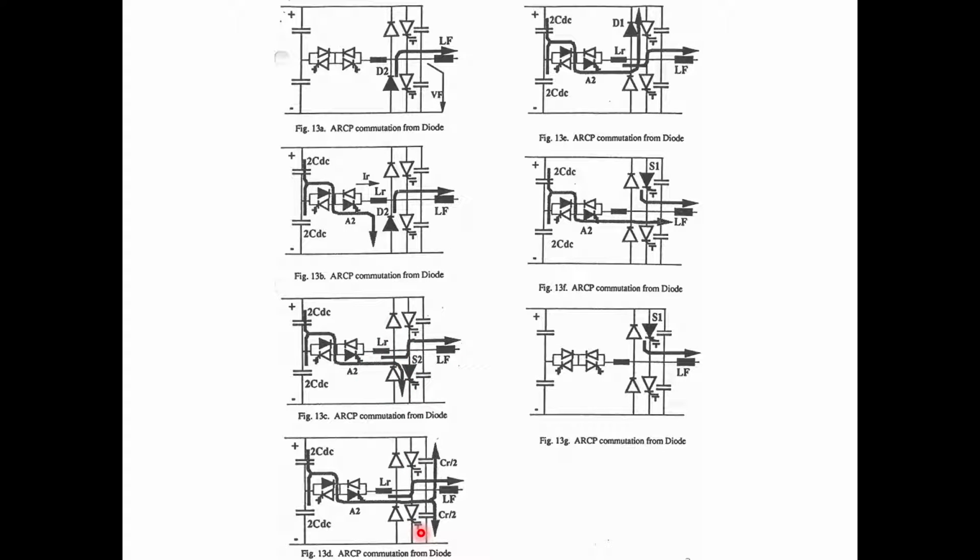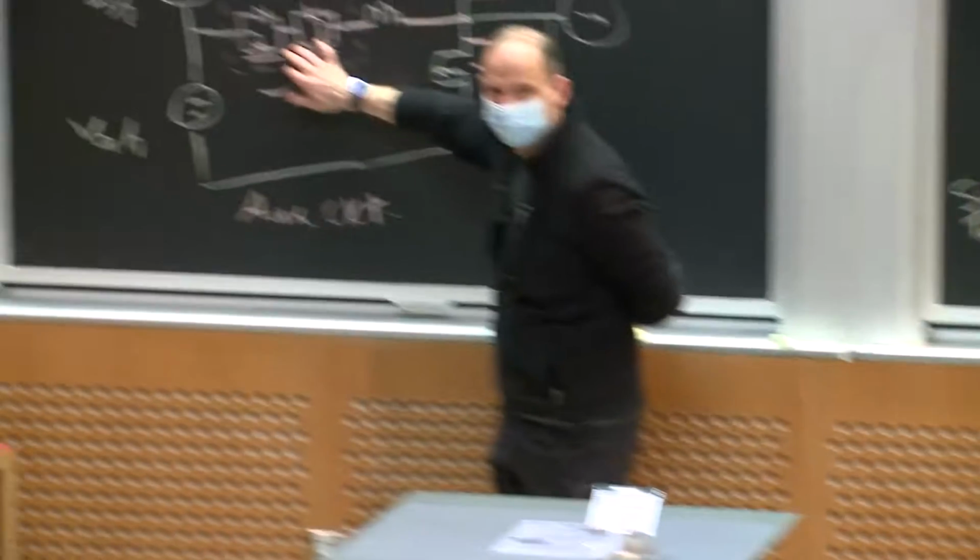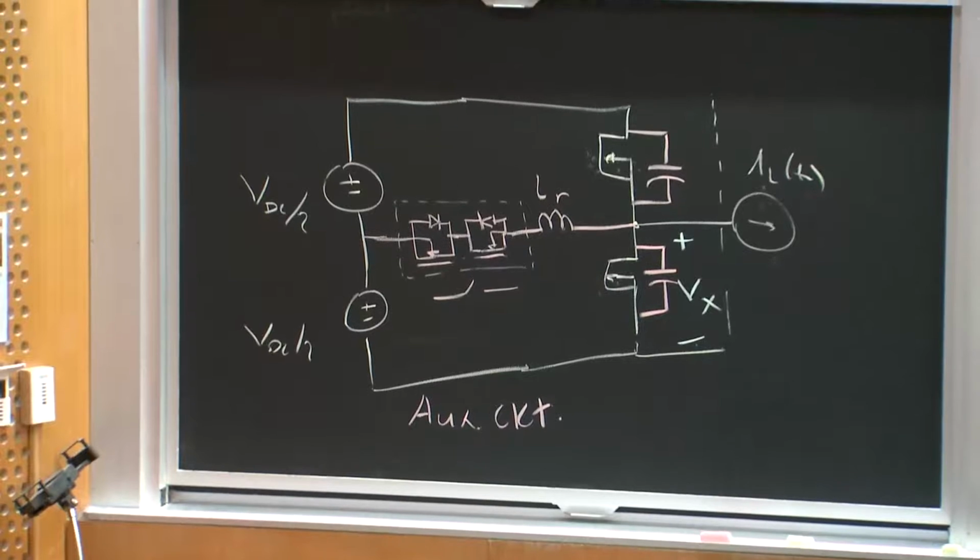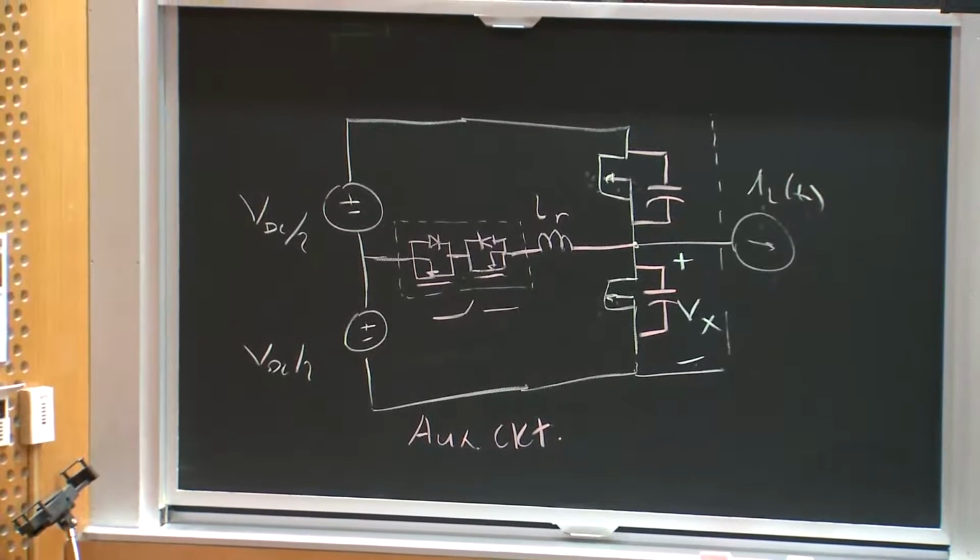And then it's very much like the other circuit, right? This resonant inductor rings with the two capacitors until the top diode conducts. Then he can turn on the top device. And then he just waits until this current ramps down and goes to 0, and this auxiliary switch turns off at 0 current, and then the top device is conducting the output current, right?